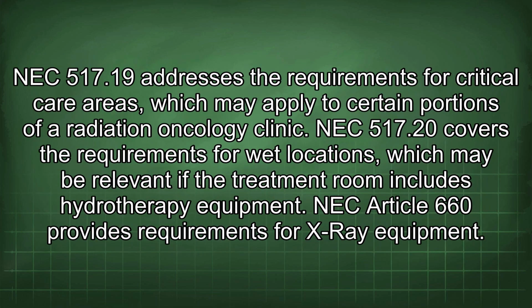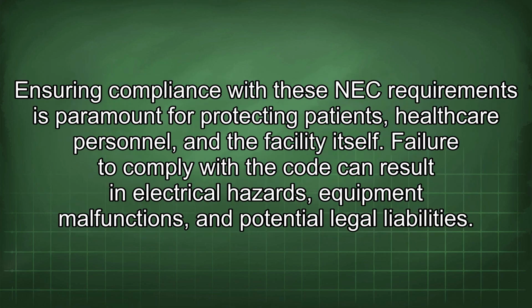NEC 517.19 addresses the requirements for critical care areas, which may apply to certain portions of a radiation oncology clinic. NEC 517.20 covers the requirements for wet locations, which may be relevant if the treatment room includes hydrotherapy equipment. NEC Article 660 provides requirements for X-ray equipment. Ensuring compliance with these NEC requirements is paramount for protecting patients, healthcare personnel, and the facility itself. Failure to comply with the code can result in electrical hazards, equipment malfunctions, and potential legal liabilities.